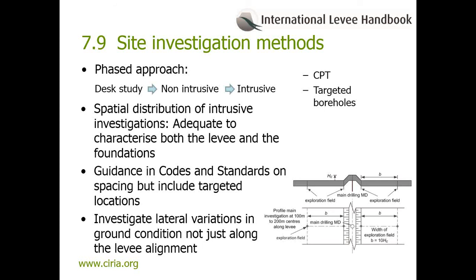Levees are linear structures. Some country codes and standards offer guidance on the spacing and depth of intrusive investigations, and these are summarized within tables included within this section. Typically, they all provide relatively similar guidance on spacing in the range between 20 and 300 meters.